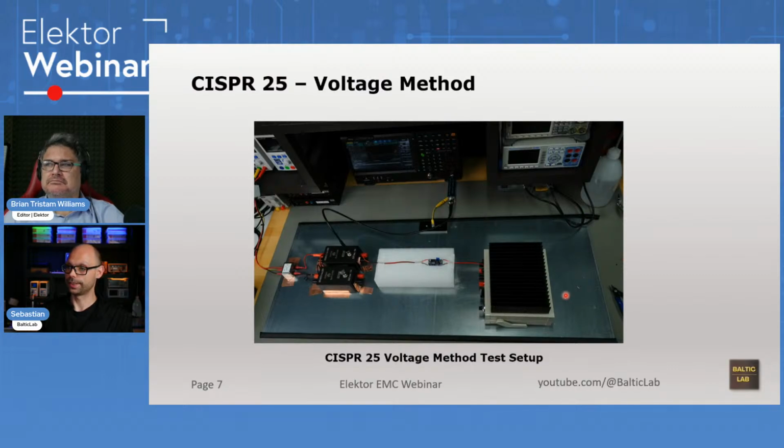It's galvanized steel, and there are also standard requirements for the size and material we'll get into later. One of the LISNs is connected to the spectrum analyzer through a transient limiter. The transient limiter is very important because setups like this are an easy way of blowing up the front end of your spectrum analyzer.